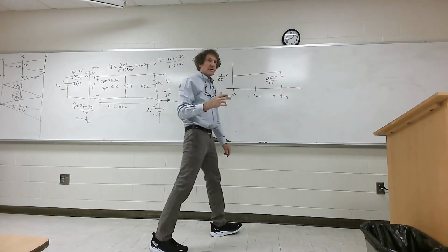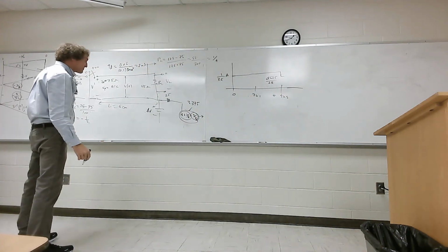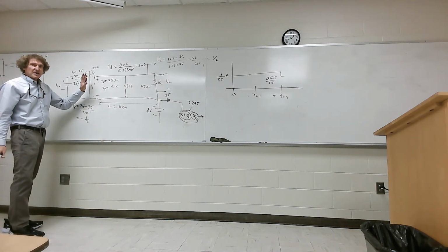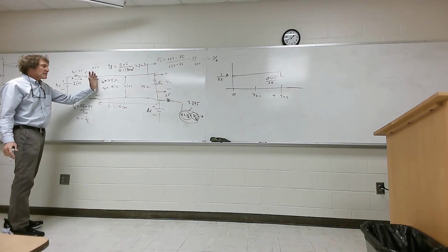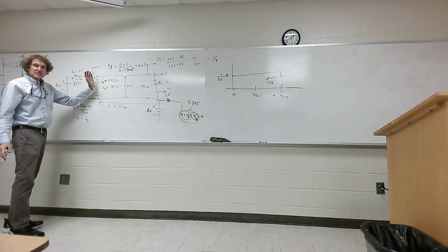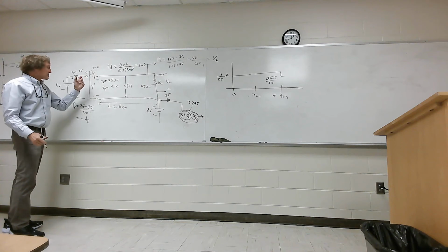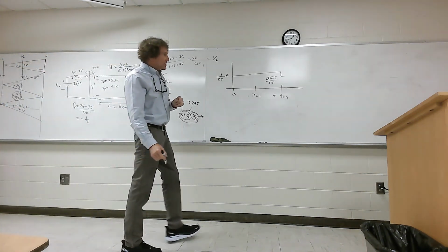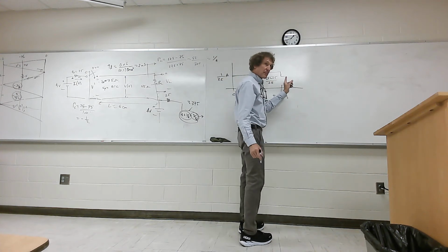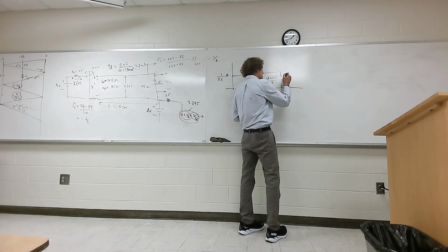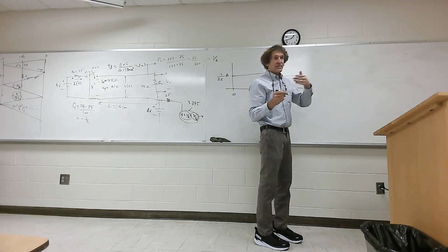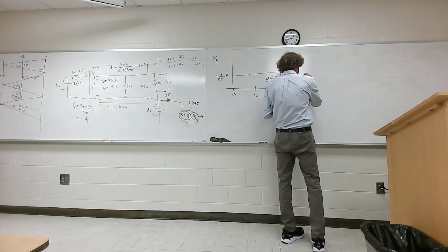Now, here's the way you think about that. Because it looks like, well, there's more voltage here, there should be more current drawn, but that's not what's happening. This transmission line already had a certain voltage developed on it. Now the change in the voltage is the only thing that's going to be accommodated by this current flowing there. So it will go from that value to this value. Do y'all follow me? And it's going to stay there until what? Now you have to go out and back again, and then you can see what's going to happen.